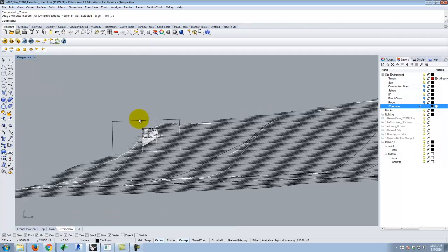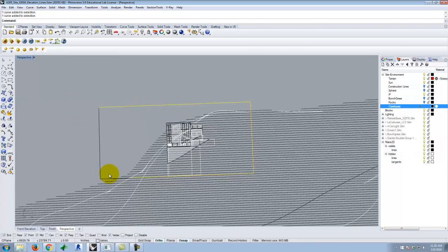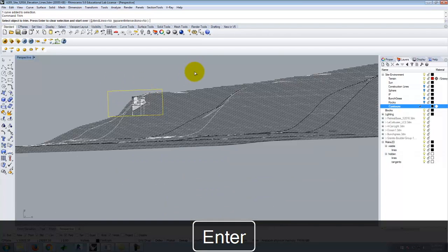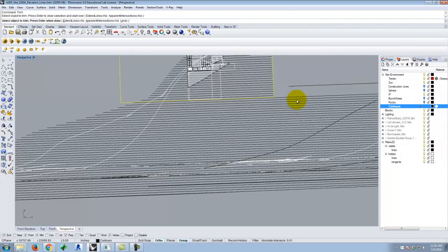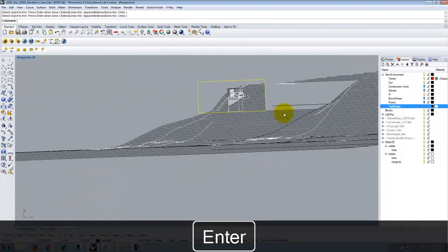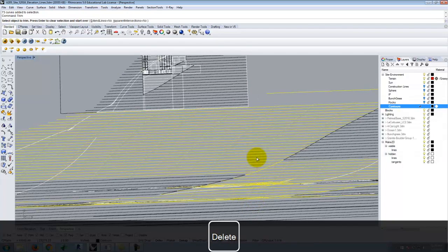Part of the reason that I drew that rectangle of my site, which is right here, is so that I knew what the boundaries of my view were. So I'm going to use these lines. We'll go ahead and select those, and select this as a trim. I'll type trim, and I'm going to get rid of the extra stuff. We'll come through here, get rid of anything extra. Then I'll go ahead and delete all this extra stuff.